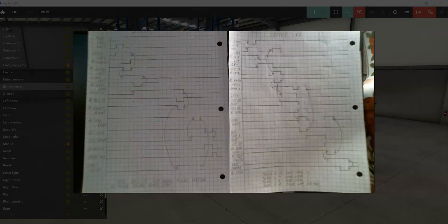Once we get at level, we can turn on the conveyor again, and we can also turn on the load right signals. That pushes it onto the load elevator cart once the elevator is at the right signal. And then we go down, and it's the same thing with the other stuff.